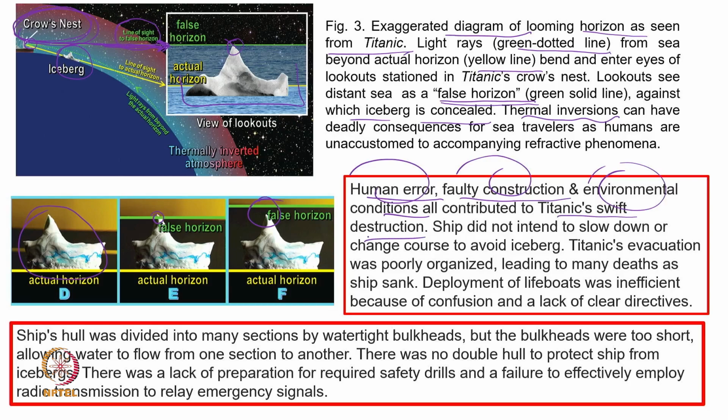Now, why am I using the word human error? The reason is, when there was a warning, at least the ship could have been slowed down, and the impact would have been much lesser. There were at least 6 warnings issued, and the ship could have been slowed and the damage reduced. Whenever there is some sort of big collision, we need to take energy into account. If there is a collision, there is a v square, the sensitivity to velocity is very high, and there is a big mass also which is going to strike against the surface. That needs to be accounted for very clearly.